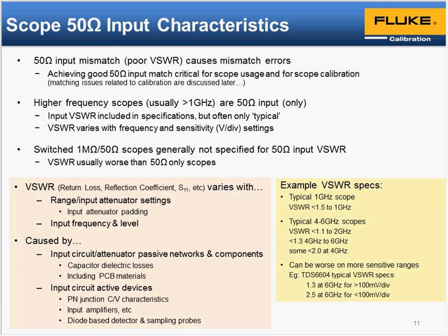So having a typical spec isn't particularly helpful, but I'll discuss more of that later in this series, which will be presented at a later date. In case that VSWR value actually varies with frequency and with the sensitivity or the voltage division setting of the oscilloscope.